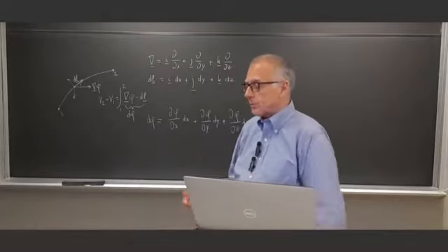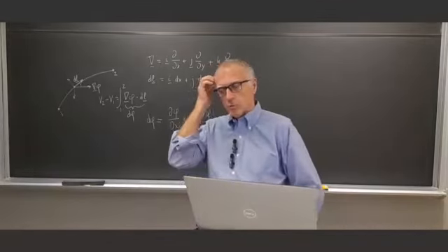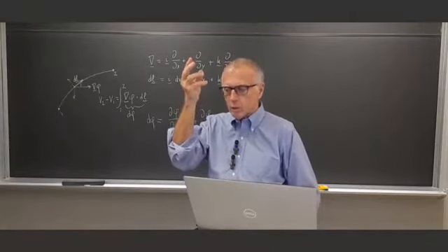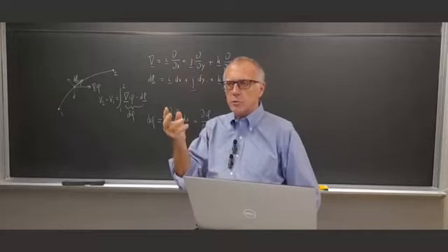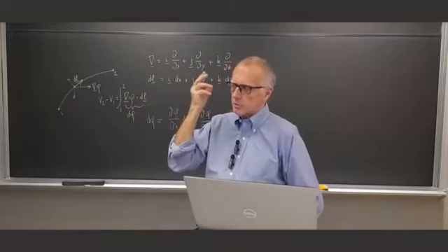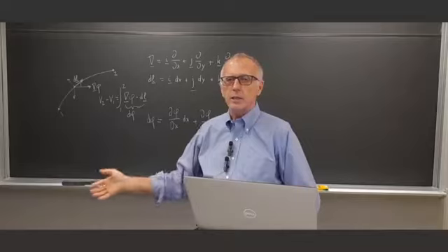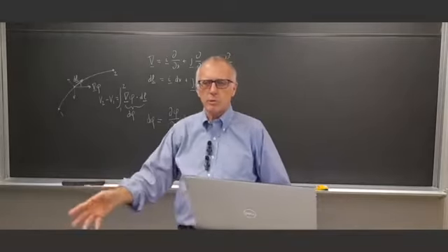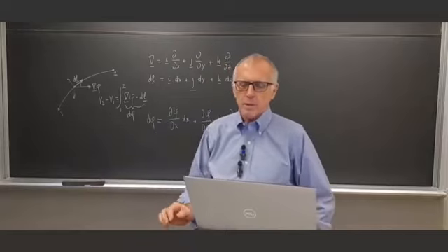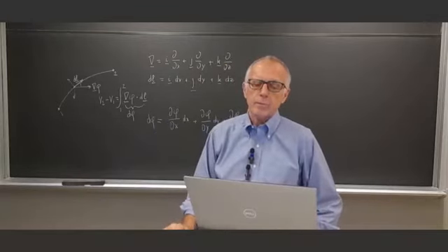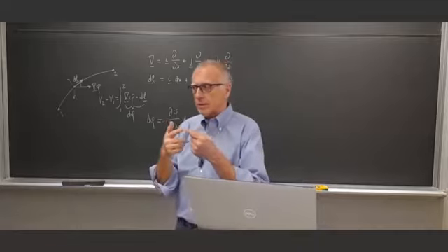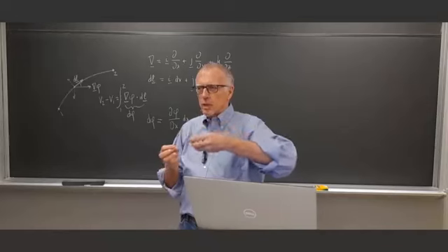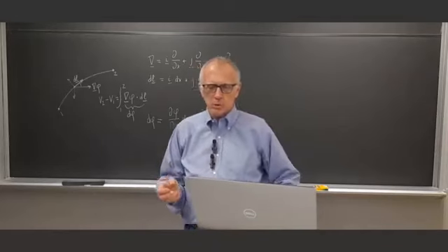Plus, in space, you have the availability of very large temperature differences, because you have the photons coming from the sun, which we just said is at 5760 K, and on the other side you have the dark space, which is maybe 2.7 or 4 K. Of course, you need electromagnetic radiation, because there is no heat exchanger. The providers of those fluxes are the photons that we just talked about.